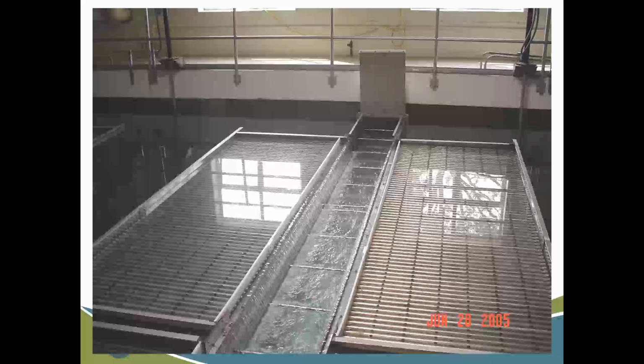I know there are several consultants that have done quite a few of these retrofit projects, and the operators that I've spoken with have been very happy with them, pretty impressed. There are some, I don't want to call them drawbacks, but you can imagine that occasionally you have to clean these plates. So there are somewhat different operation and maintenance challenges with a plate settler than with a conventional settling basin. But on the whole, I think everybody's more than happy to spend the additional time required to clean these plates and keep them functioning properly compared to the alternative of having a much larger basin in order to get the required settling time.